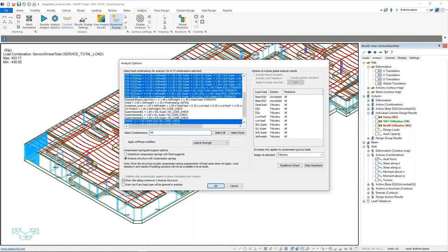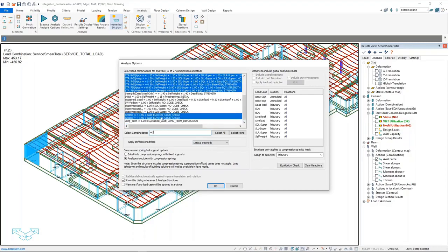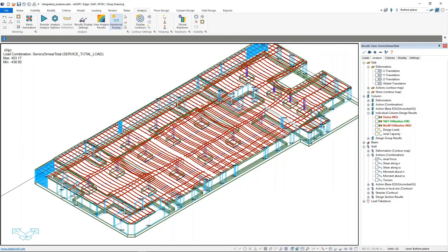I'm only running my load cases for EQX and EQY under lateral strength. That means that the reactions in the walls and columns will be based on my reduced stiffness. If you remember when we did the mat, I would then say, oh yes, I remember my EQX should really be coming from this lateral strength, not from my uncracked, which I'm using for gravity. So I hope that addresses that question of how to handle the assignment of cracking for the shear walls.